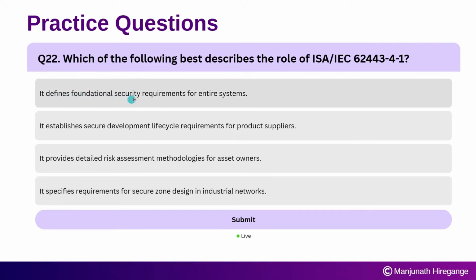It defines a FR, foundational security requirement for the entire systems. It establishes secure development lifecycle requirements for product suppliers. It provides detailed risk assessment methodologies for asset owners. It specifies the requirement for secure zone design in industrial networks.